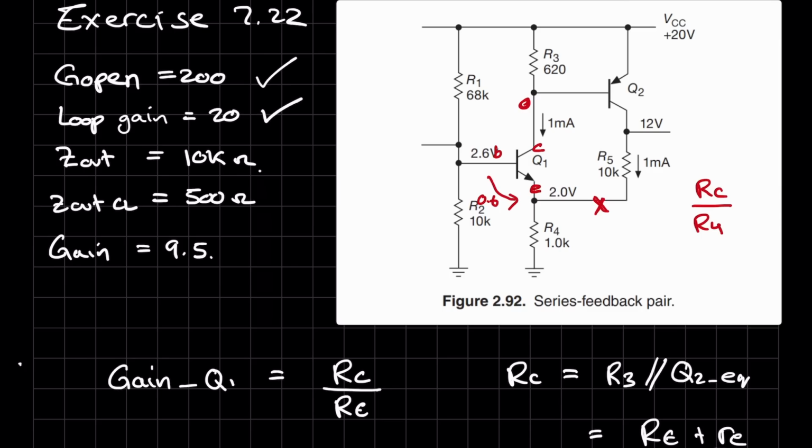The output impedance for this circuit is very simple. You can see we have basically just this resistor over here that's before the output signal. So our output impedance for the open loop, when this is disconnected, is basically this 10 kilo ohm resistor over here. Now when this is disconnected, this would most likely be grounded. So that's 10 kilo ohms that's coming straight from R5.